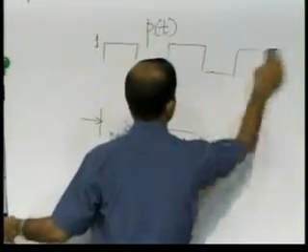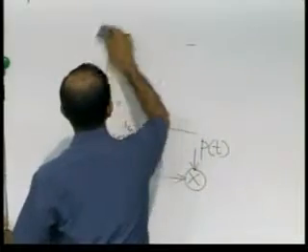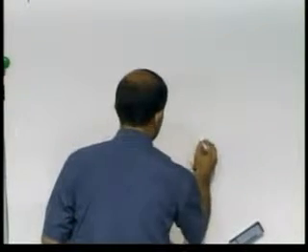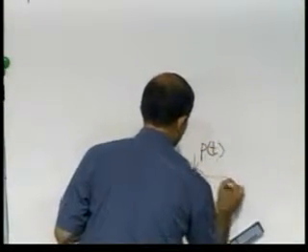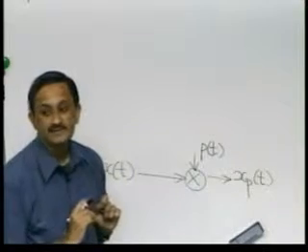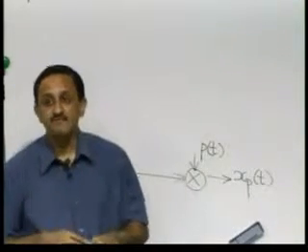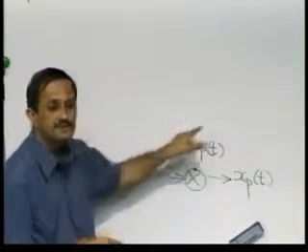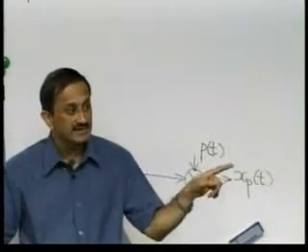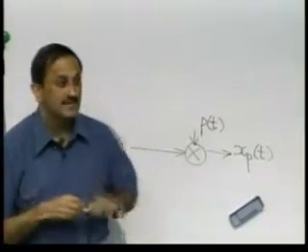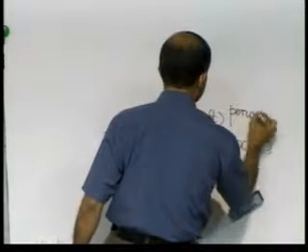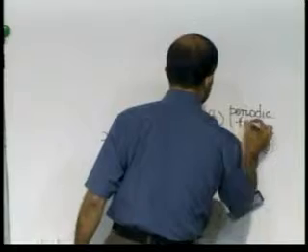So, you see, if p(t) is periodic with a period Tc, the product waveform x_p(t) here is going to have a spectrum given by the convolution of the spectrum of x(t) with the spectrum of p(t). And what is the spectrum of p(t)? It is a train of impulses located at all multiples of 1 by Tc, which we shall call Fc. So, p(t) is periodic with frequency Fc.